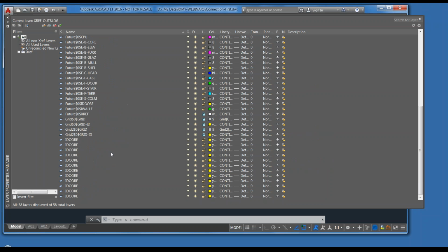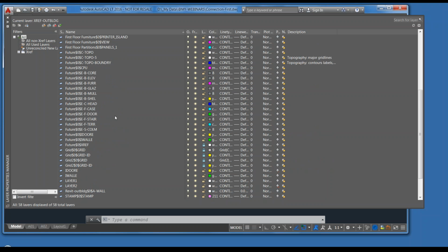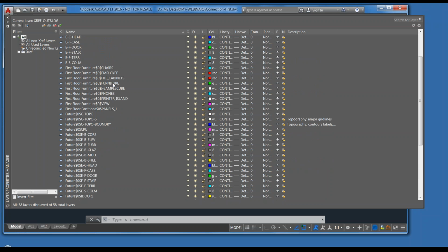This can get pretty lengthy for some drawing names, and there's repetition too, potentially. So if you have a wall layer in one drawing, a wall layer in another, and yet another wall layer in a third drawing, you'll have 3 different wall layers in this bound version.